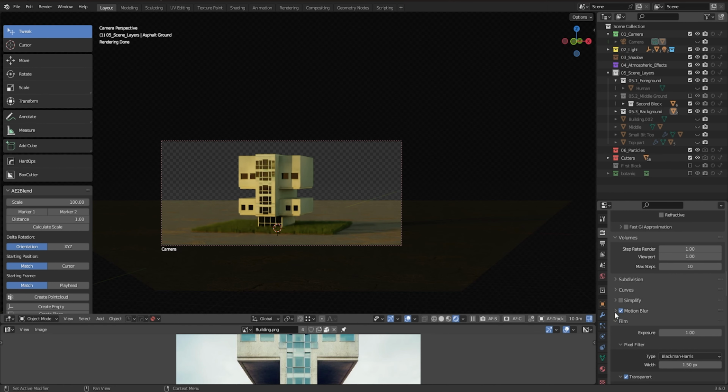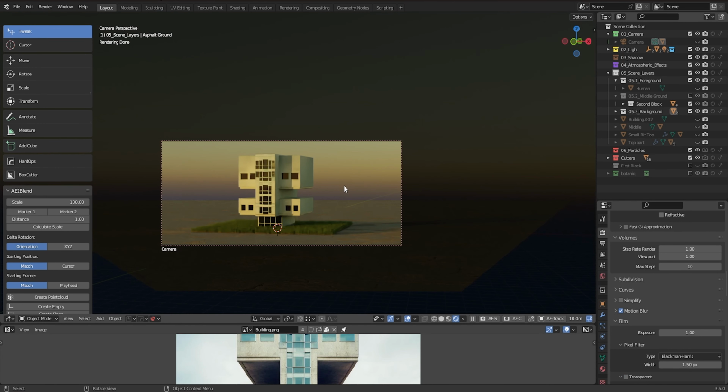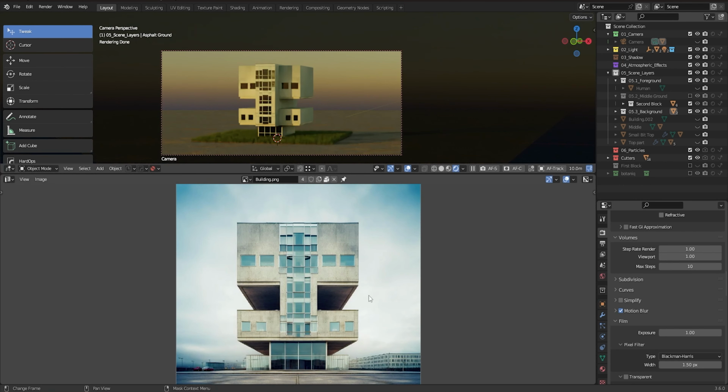So just to summarize, when we are doing the cuts in the object itself, let's use the knife tool because that maintains the texture. When we are blocking everything, we use the intersect. You can also use the cut, but I prefer to use the cut in the beginning when we are doing the bigger shapes, meaning cutting these areas here, cutting these areas here, cutting these areas here, and then I just separate everything.